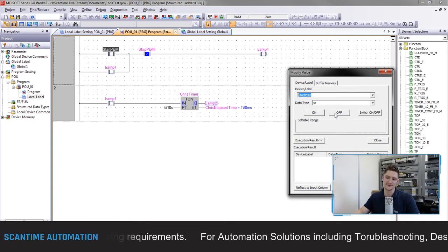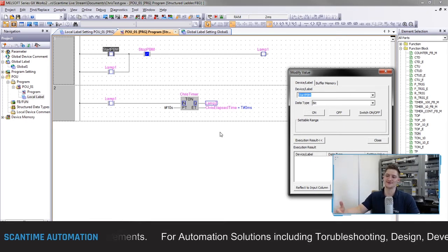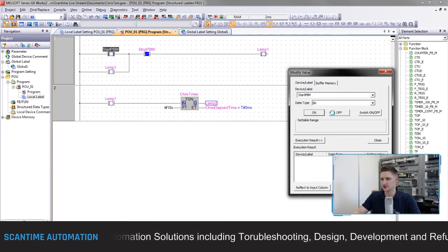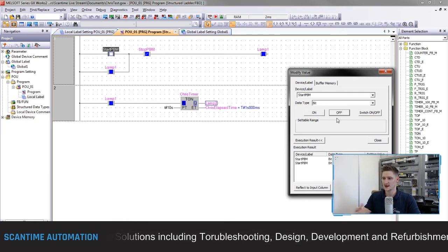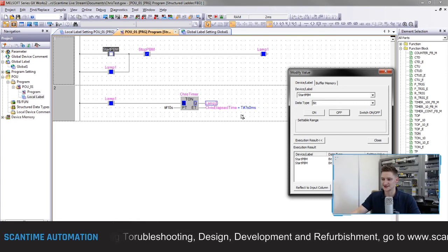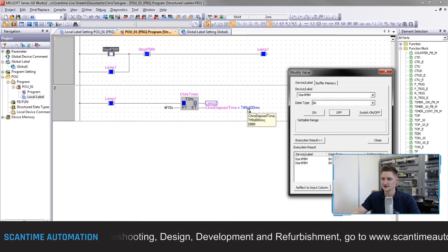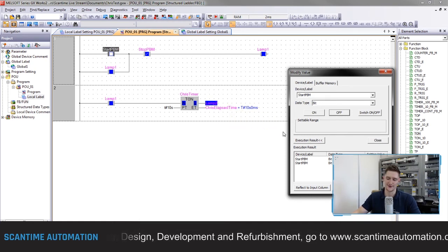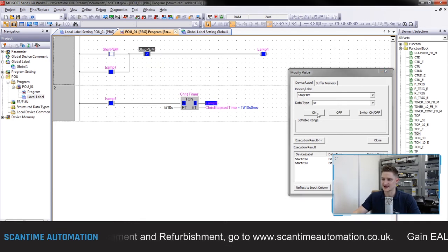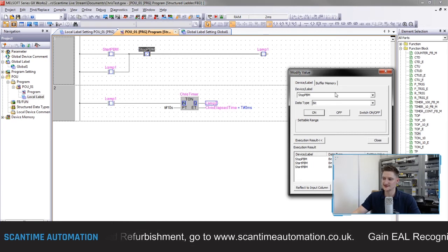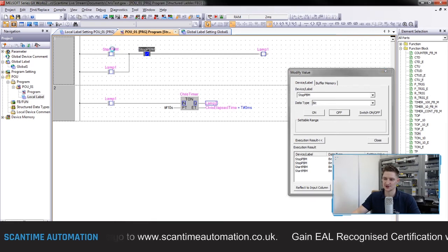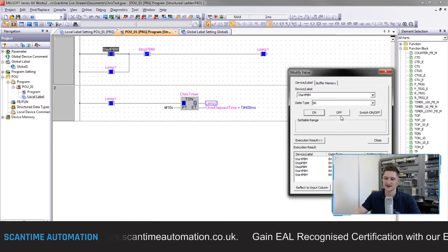and then our timer will begin running. After 10 seconds, our timer then turns on lamp 2. So 3, 2, 1, switch it on, switch it off, and there we go. Our latch is currently enabled, our lamp 1 is currently on, our timer is now currently running. 10 seconds later, our lamp 2 now turns on. If I then select my stop PB and then select that as on, it then resets my latch and then resets my timer back to 0. If I then trigger the start once again, it'll begin counting once again.